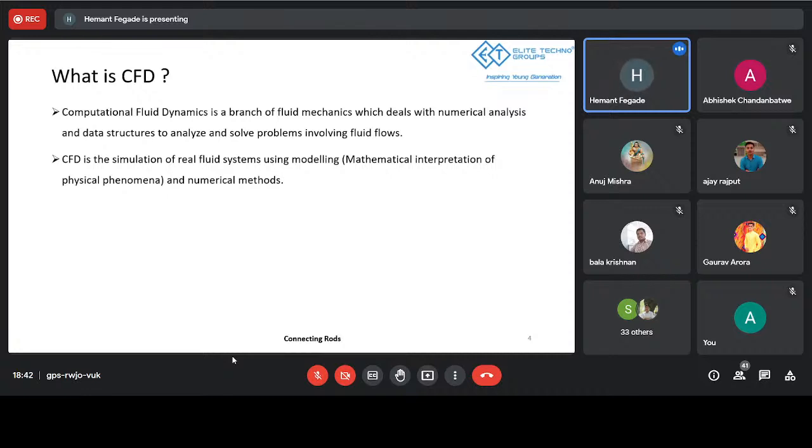How are we going to predict or calculate these numerical values, these parameters? Computational fluid dynamics uses numerical methods to resolve the quadratic equations into linear equations or linear matrix formulations, and that linear matrix formulation is then used to solve and calculate the value of a parameter, for pressure, let's say, at a particular point at a particular section. That's how it is basically being used.